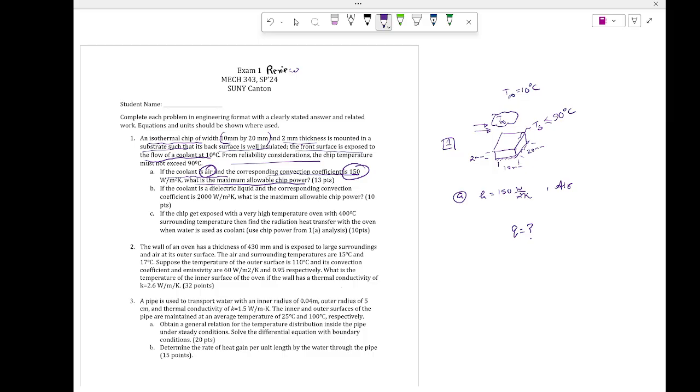So can you find the area A for all the surfaces separately? You're going to have the total A value, where you have five sides. The top surface is one side, and there are four more on the sides. The bottom surface, do you care? No, because it's insulated, so no heat transfer. So there are five surfaces. You can find the area of the five surfaces, and then you can use which equation again? The convection equation, which is equal to h A delta T.